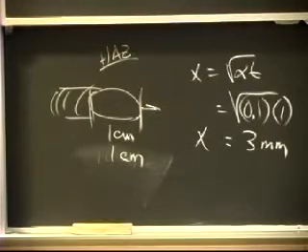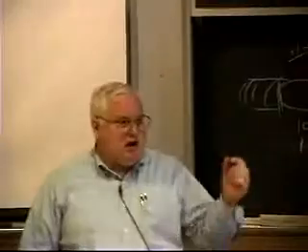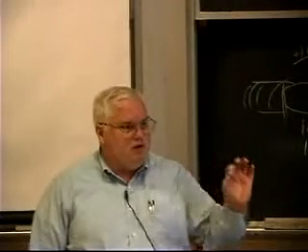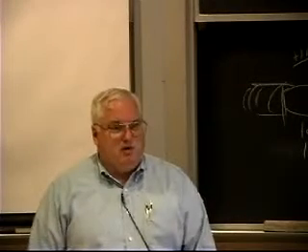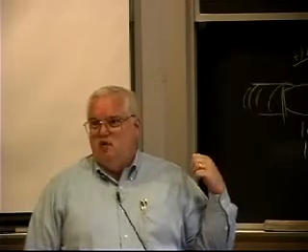Okay, so is that about the width of the heat affected zone? If I had that piece of HY80, you pass it around, yeah, it's about 1/8 of an inch. Is that the little heat affected zone you saw in the HY80? It's about 1/8 of an inch in size. I just calculated it, order of magnitude.